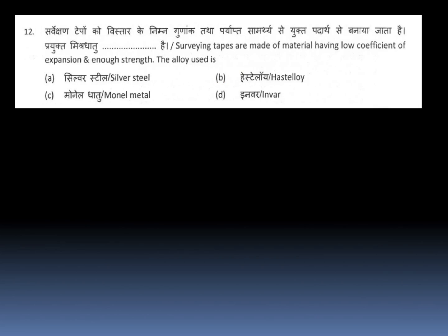Surveying tapes are made of material having low coefficient of expansion and enough strength. The alloy used is Invar. This same type of question they also asked in IES. Invar is the answer. Percentage is 64 by 36. It's a nickel alloy. Iron 64, nickel is 36.